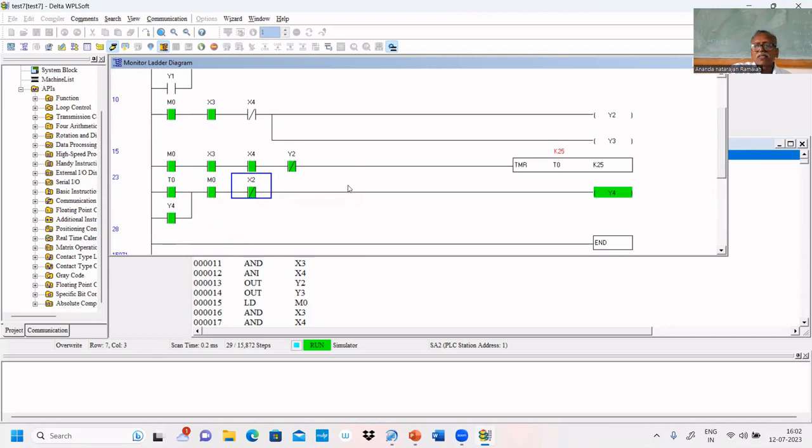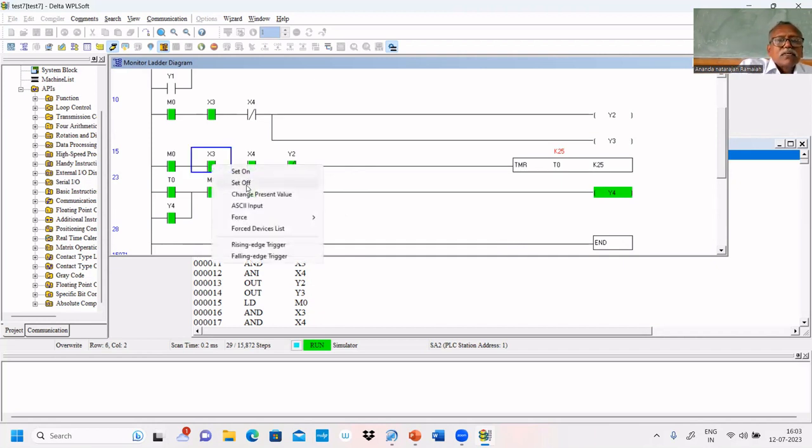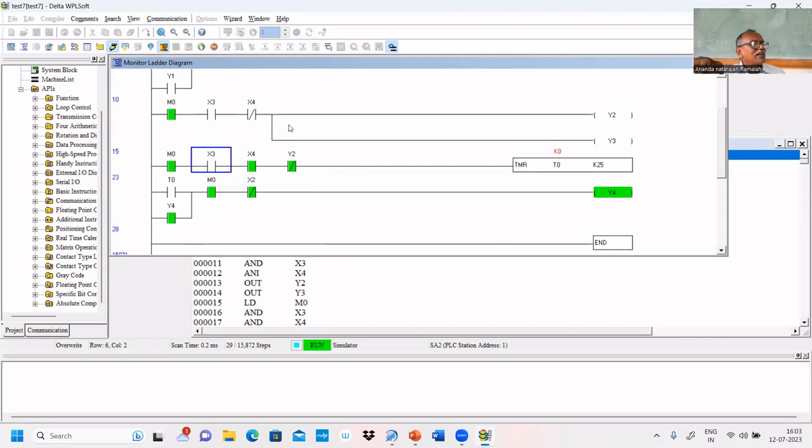What happens here? After a delay, the outlet valve is opened now. The outlet valve is opened. Now it is draining. We have to imagine it like that. Now the tank is draining. First, what will happen? First X3 becomes 0. So we have to change that first. Still, the valve is open. It is functioning correctly.